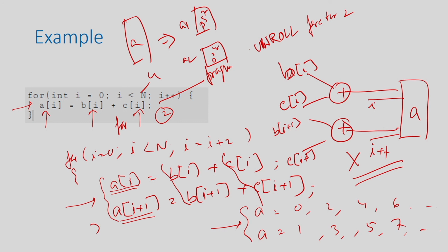So, the key takeaway or the key summary that I want to make from this slide is that blindly doing partial unrolling may not help, because loops always come with arrays, and the array access is increasing. If you assume that I am just doing unrolling and I will get the desired performance improvement, it will be bottlenecked by the array accesses. So, once you apply partial unroll, you have to make sure that you partition the array based on its access pattern, right. If you partition the array in that way, only then will you obtain the required performance benefit, otherwise you will not get that.